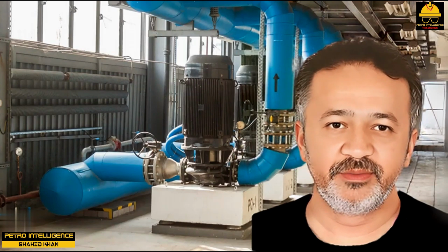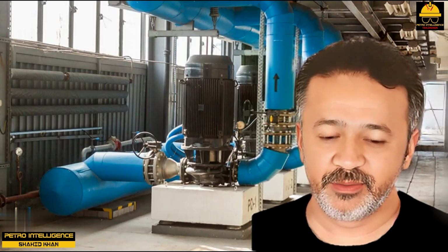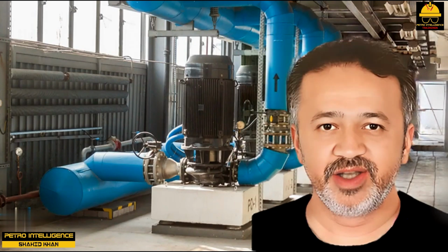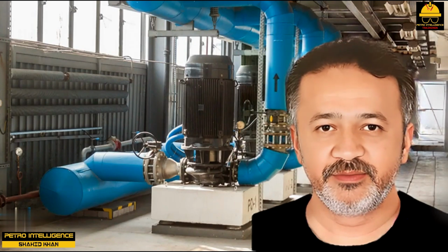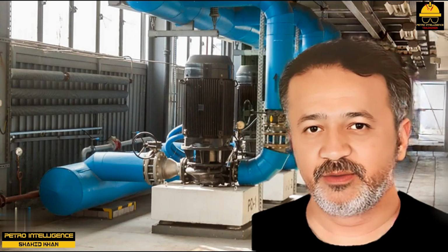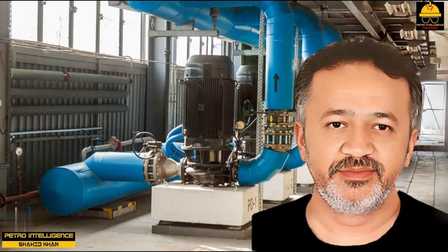The amp meter for a pump is best located right on the start-stop box next to the motor. Unfortunately, more often, the only amp meter is located on the electrical breaker box, which is at a remote location.